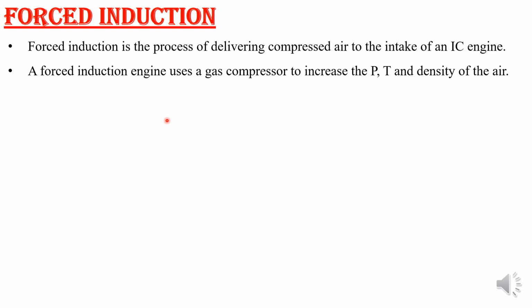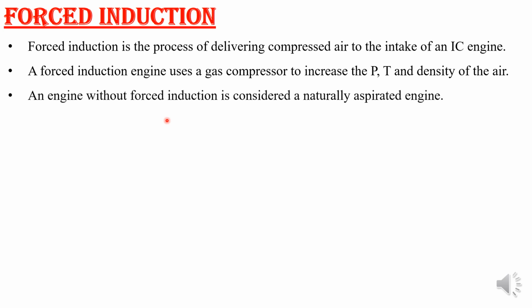An engine without forced induction is called a naturally aspirated engine. Means normally it will take the air as it is by sucking, that is 1 atmospheric. That type of engine is called a naturally aspirated engine. Forced induction engine means we are forcibly making that higher pressure, air density. So some device we will use, and that type of engine is called a forced induction engine.